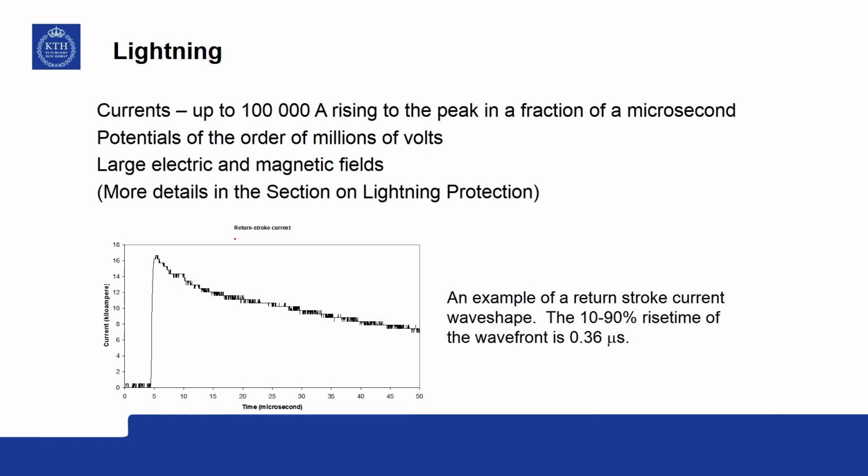Now, let us look at lightning. What is shown here is one small portion of a lightning current waveform. It is called a lightning return stroke. We will see more details of lightning when we discuss lightning protection. Here this is the time; the time base is in microseconds. The total time is 50 microseconds here. The whole lightning flash may last up to 1 second with several events in it.